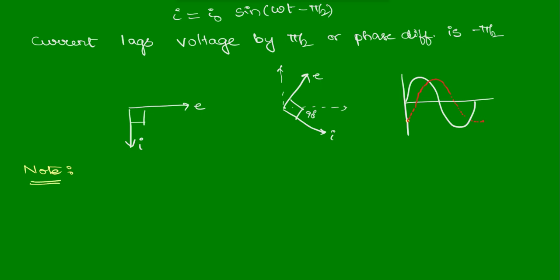So as we got like this, current is equal to voltage by resistance. We can write like this: resistance will be equal to voltage by current, and there is no phase difference between current and voltage in a pure resistive circuit, so that resistance also we can represent in a phasor diagram with phase angle 0. And similarly this is for the resistive circuit.